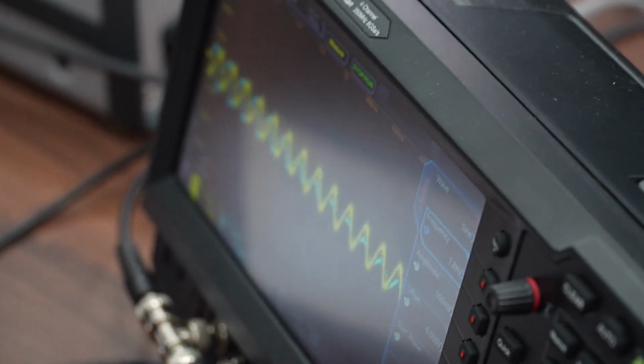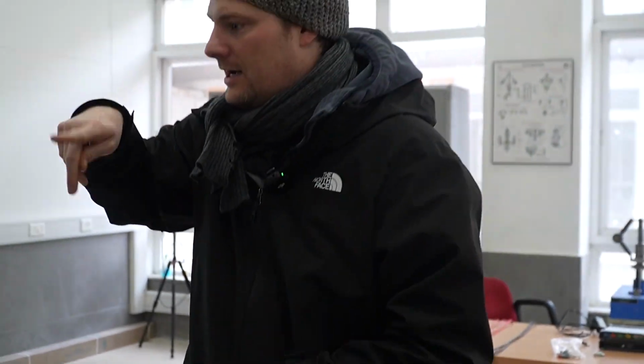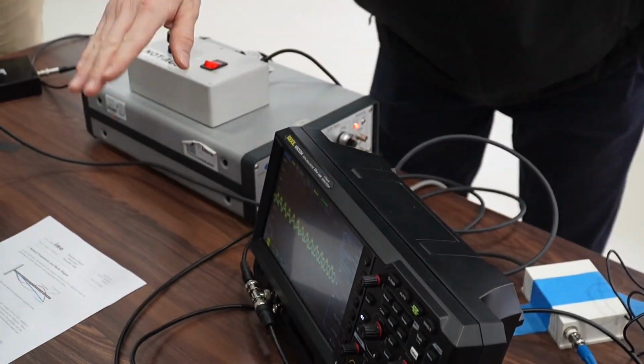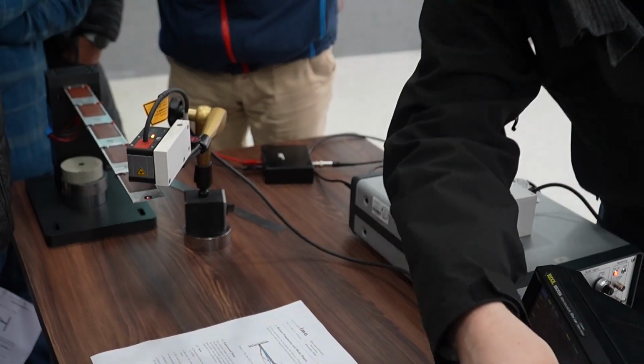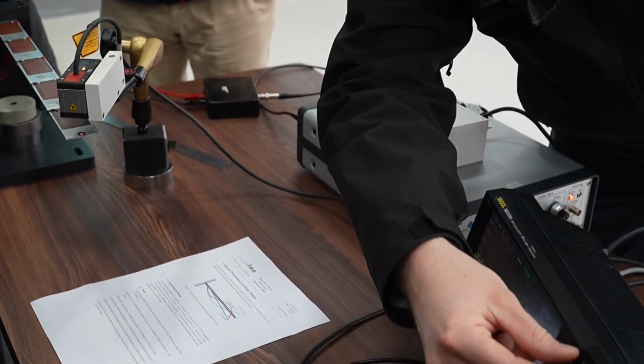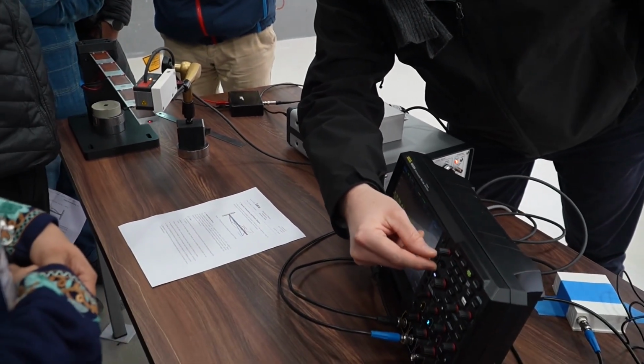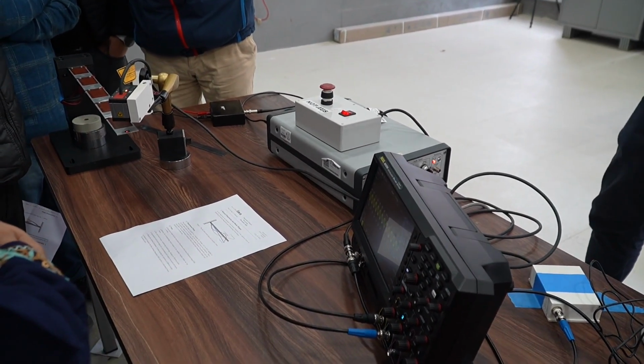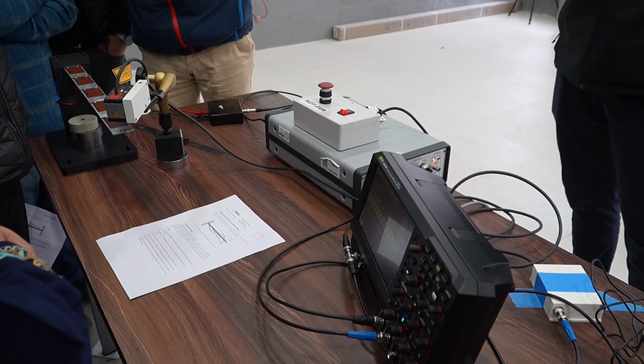If two frequencies are very close, then you will get something like it goes up and down and up and down. And this is what we see now more or less. And then if we go even higher, then it basically stops. So if we go back and we excite directly in this, what was it, 7.5? Yeah. If we excite directly in the eigenfrequency, then we get huge amplitudes.